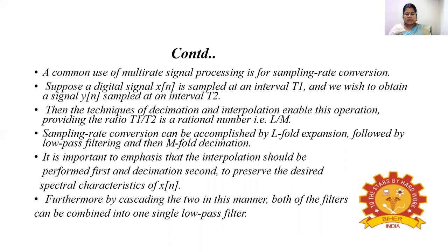This can be accomplished by an L-fold expansion with upsampling, followed by low-pass filtering and M-fold decimation.